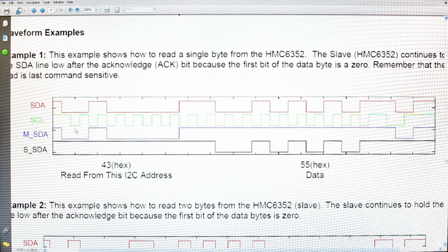So here's our start bit, and then the device reads on positive-going edges of SCL. Look at master SDA right here, and you've got 0, 1, 0, 0, which is 4, 0, 0, and then a 1, which is the last address bit, and then a 1 indicating that it wants to read, because it says read right there. So now the master lets that line stay high, and the slave goes, okay, I got it. And then the slave starts transmitting data according to the SCL lines.